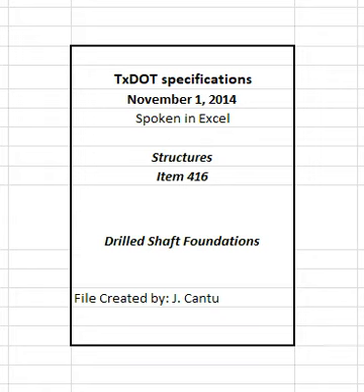3.2 Core holes. Take cores to determine the character of the supporting materials if directed. Use a method that will result in recovery of an intact sample adequate for judging the character of the founding material. Such cores should be at least 5 feet deeper than the proposed founding grade or a depth equal to the diameter of the shaft, whichever is greater. Take these cores when the excavation is complete.